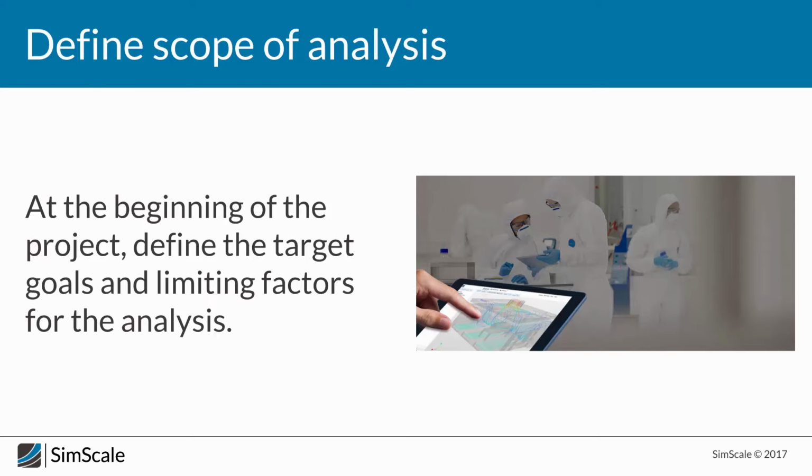It might be enough for us to take a look at a small portion of the whole phenomenon that is going on, like seeing the particles being moved or a passive scalar that is being distributed. It might not be required to take a look at the temperature behavior or buoyancy effects, which will not be significant enough to change the flow within the room.